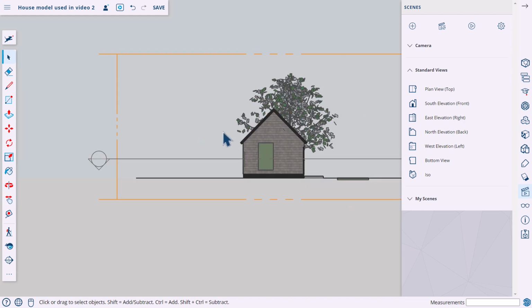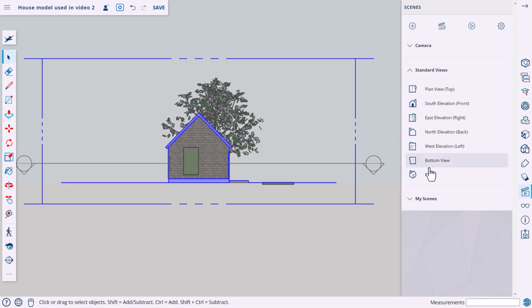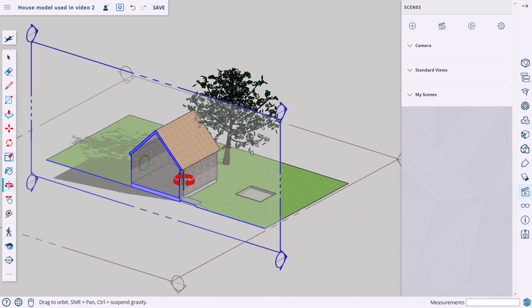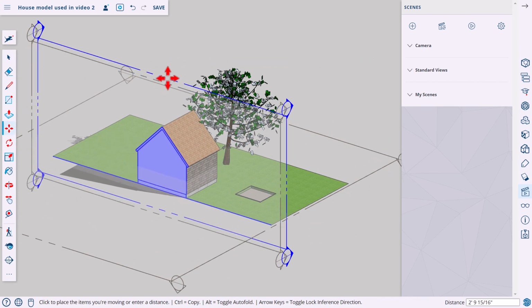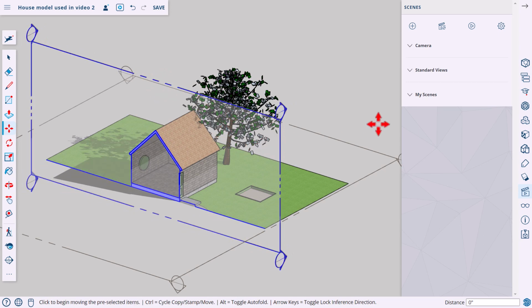One thing to be aware of, by the way, when you save that section view is that the section planes are visible here in this view. That's a different thing than the cuts themselves. You can turn on and off a cut by basically double-clicking on the section plane. You see how it turns it on or off. In fact, you can even move the section plane just using the Move tool. It's an object like any other, and you can see how it behaves differently depending on where it's cutting through your building.